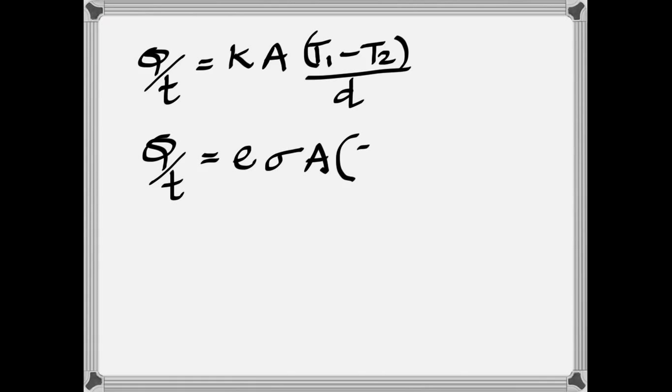Now another formula, for radiation. Quantity of heat radiated, Q equals eAσ(T1 raised to 4 minus T2 raised to 4) times t. Q stands for the quantity of heat radiated. Because there are three ways in which heat can be transferred: conduction, convection, and radiation. You don't have a formula for convection. You only have conduction and radiation.